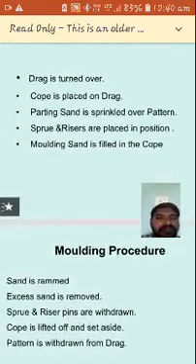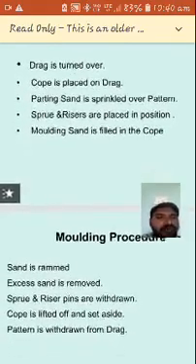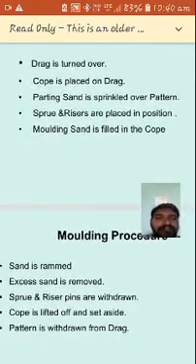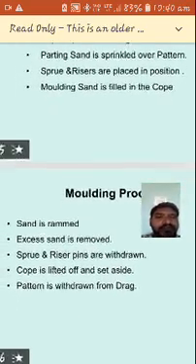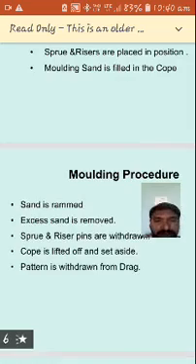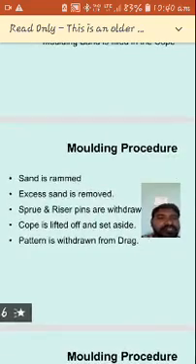Okay, so the molding sand is filled in the cope. Molding sand, you can completely fill it. After filling, you can go for the ramming operation. By using a rammer you can go for the ramming. At the corners also you are going to fill it. The excess sand is removed by using a strike off bar.